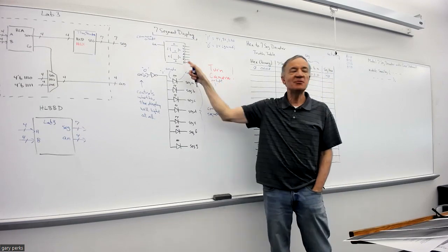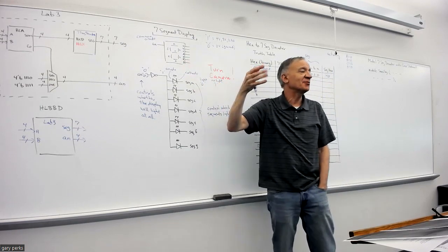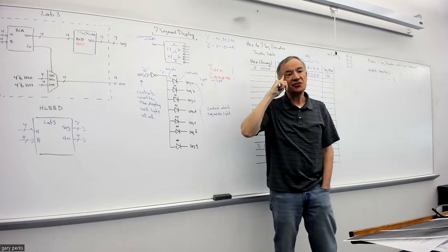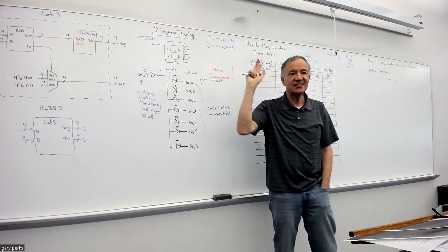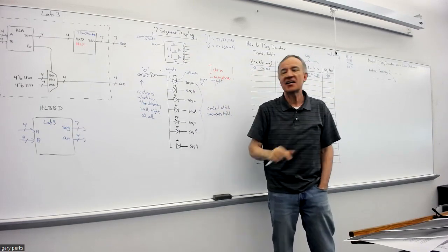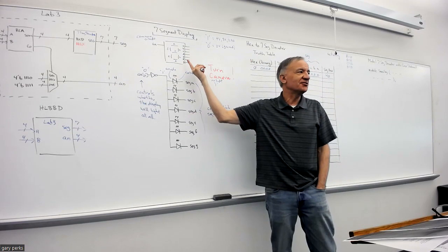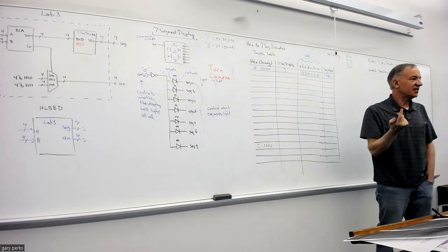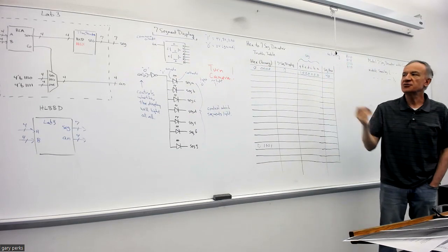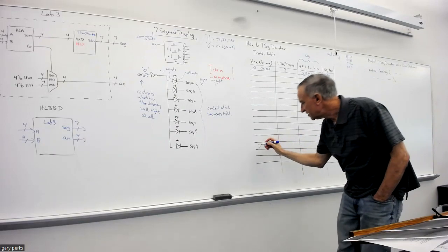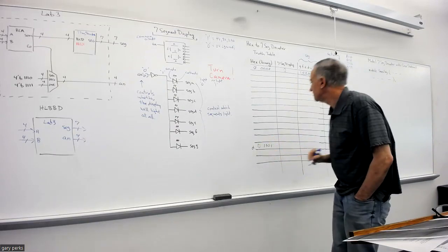And that's because of the limitation of this display. It only has 7 segments. There's other types of displays that have more segments. You can get a display that has like 16 segments and they have some at angles, so you can make like W's and things like that. But we're restricted because there's only 7 segments. So because a capital D would look like a 0, we'll use lowercase d. So instead of a capital D, we'll use lowercase d.